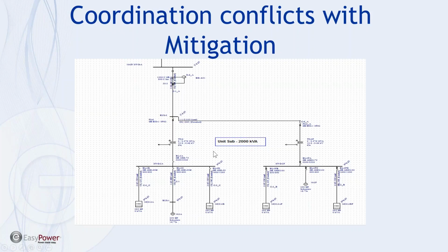The bottom line is, if we have a one-line diagram similar to this, where we're trying to coordinate with a large load in a remote feeder bus, then we want the first inline breaker to trip first, the second breaker upstream to trip next, and then in sequential order the trip devices upstream of that. Which means if they're all similar type breakers, we have to slow down the response time of the upstream breakers to accommodate that differential in time.